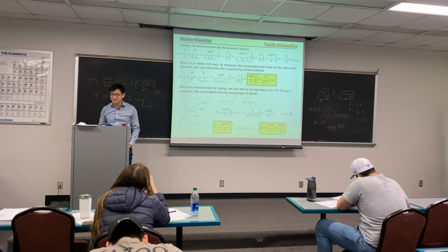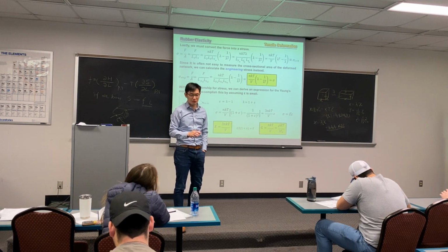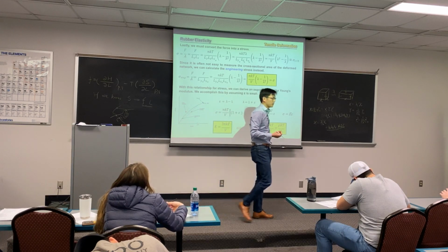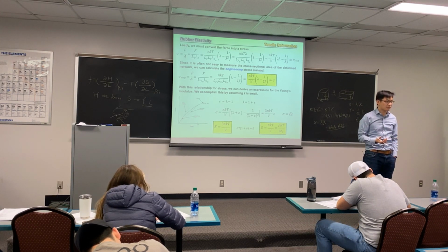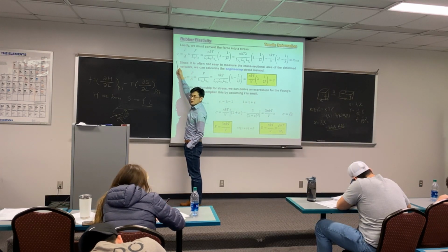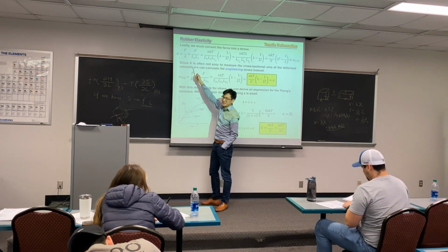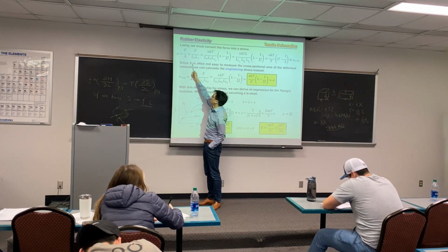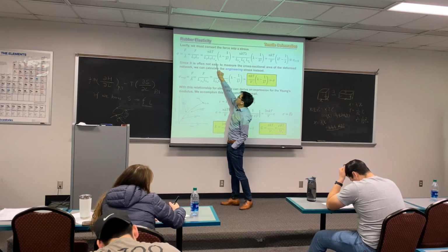All right, we're halfway. What's left? This is probably the other most important slide we want to talk about. This tells you how we can convert the force to the modulus of your rubber band string. How can we predict the modulus for the rubber band? We can get the stress. Everybody knows how to get the stress from Sergei's class, I hope, by now. Force divided by area. And we know the area is the area in the y and z direction. So you take force divided by Ly and Lz, which equals this equation.